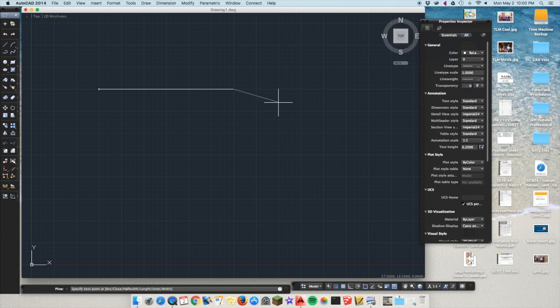So the polyline tool, if you look down in the command bar, gives you an option to now change from a line to an arc. So I'm going to type A for arc and hit enter. And now you can see that there's an arc there. I want just kind of a gradual curve, like a Frisbee would curve. So let's go out to maybe here. Then it's going to come out a little bit here and down so that your fingers could go underneath there.